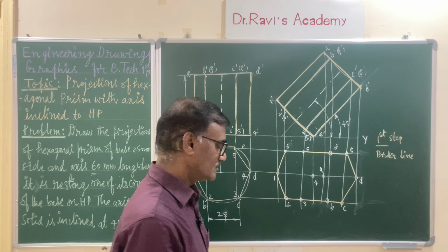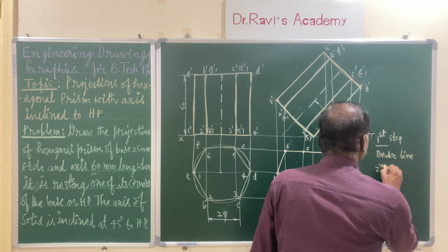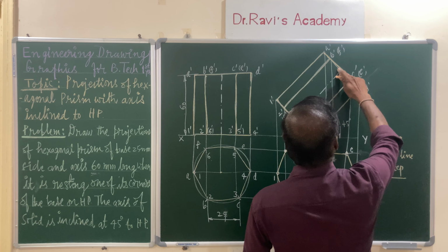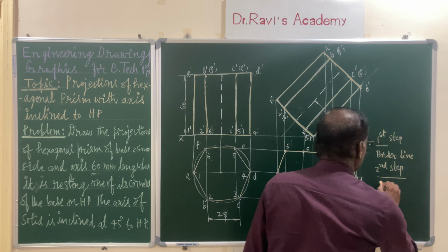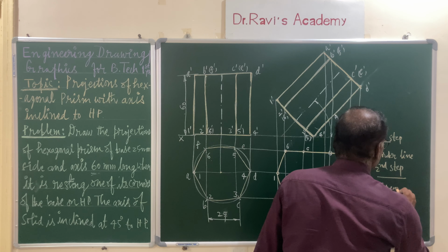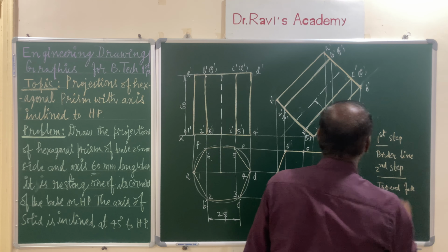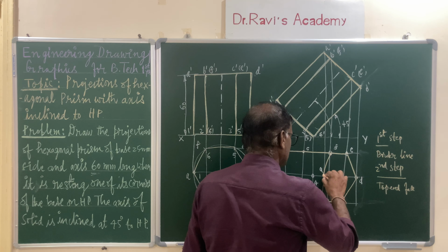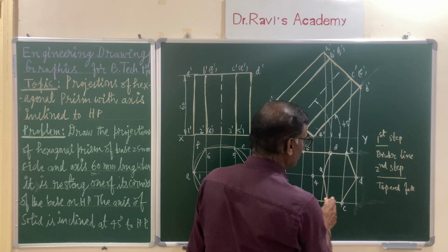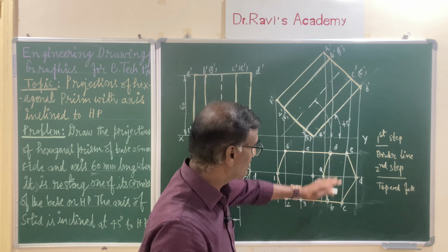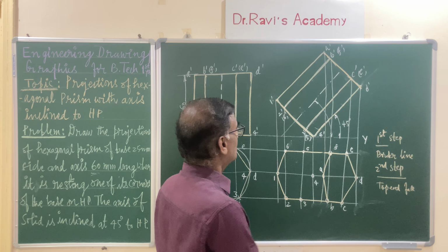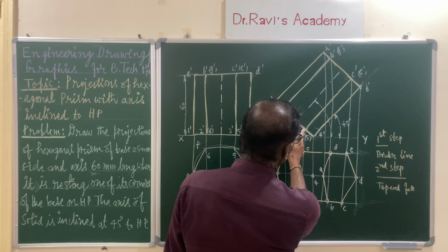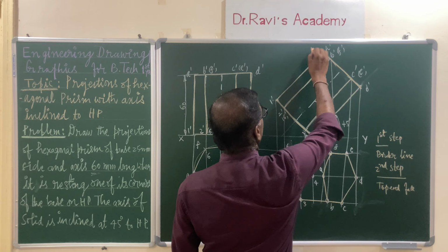using HB pencil. Your second step is join the top end face in which you have all visible edges. Top end face is completely visible, that is with alphabet. So, you can join with HB pencil and AB as well AF, all others are already joined with the border lines. Now, bottom end face, observe carefully here 3, 4 and 4, 5 which are not visible in top view,